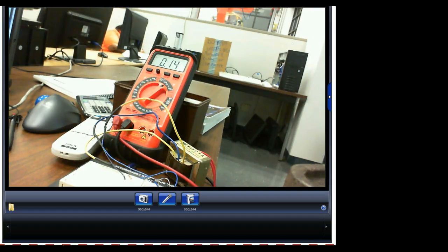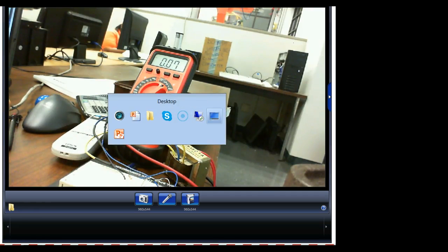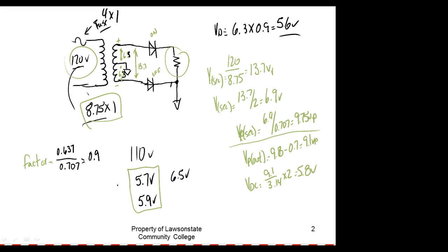So we could do that on our, would you see where the 9/10 came from? Isn't that neat? So basically we're converting it to peak and converting it over. By the way, what would a half wave rectifier be? Well, since we lose that half cycle, you would take that answer right there and divide it by 2. Do you understand why? Because this would be the average if you're getting both alternations. On a half wave, we're getting half the alternation. We're getting a 0 the other one. So if you divide that by 2, it should come up to be what we got a while ago.